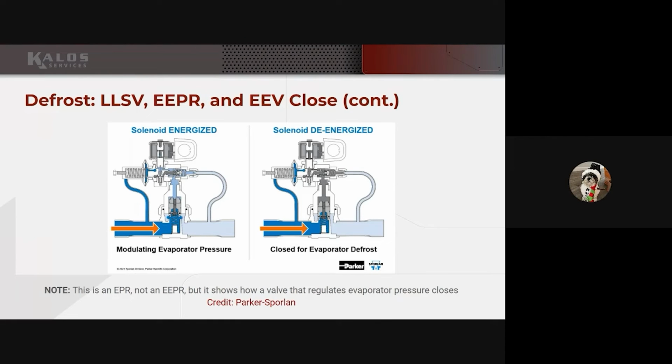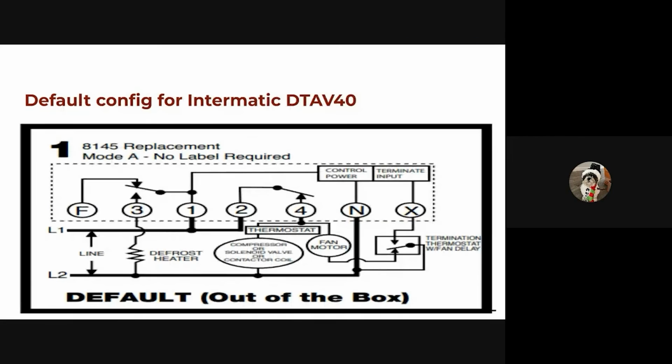So when we want cooling, provide power to it. Okay, so that's the opposite though. So we're providing power. Okay, good. We can slow down. Help me understand this better. De-energize means no power to it, and it shuts the valve. When it comes out of defrost, there's power applied to it, and it opens it up to allow refrigerant to go through. And then our fans.